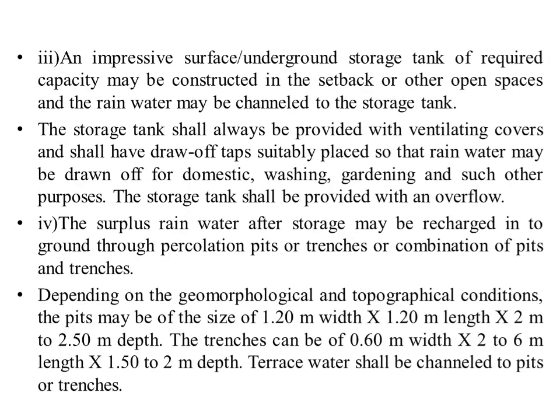All new buildings to be constructed shall have an installed hot water line from the rooftop and insulated distribution pipelines to reach the points where hot water is required in the building. The capacity of the solar water heating system to be installed on the building shall be described on the basis of average occupancy of the building. The norms for hospitals, hotels, and other functional buildings are given below.